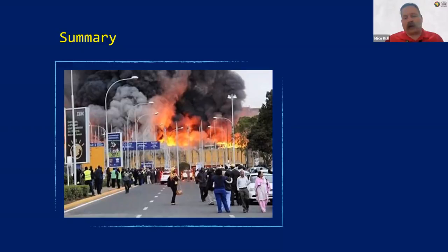And then we spend a lot of time talking about collapse, figuring out what our collapse zones may be, looking for those indicators of collapse: smoke from the cracks, bulging walls, paint blistering, windows cracking, windows completely blackened over, all those different indicators of what the fire's doing inside the building. So that's just a quick look at scene size up and what we might want to be doing there.